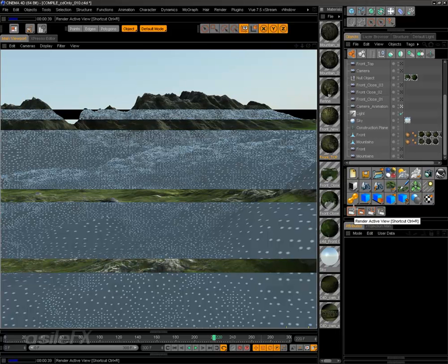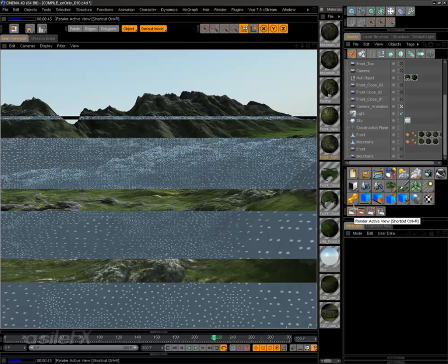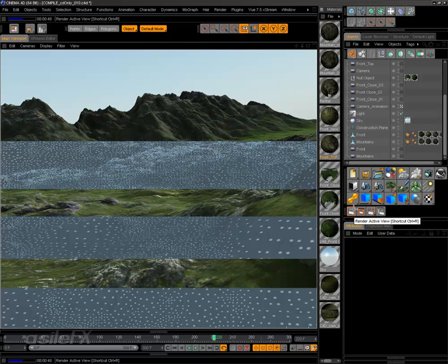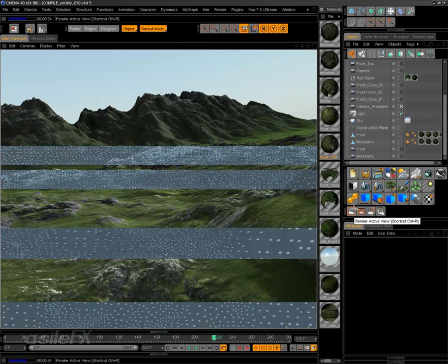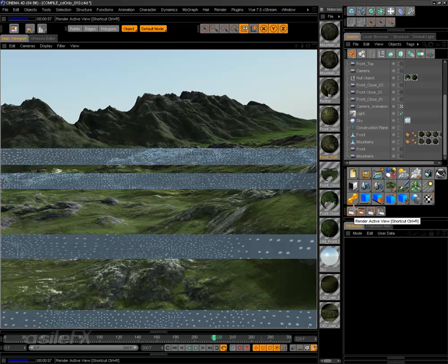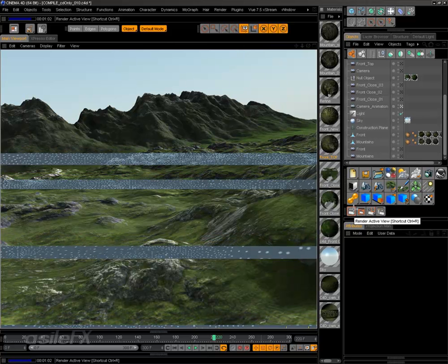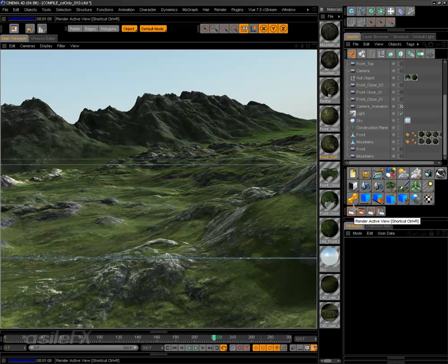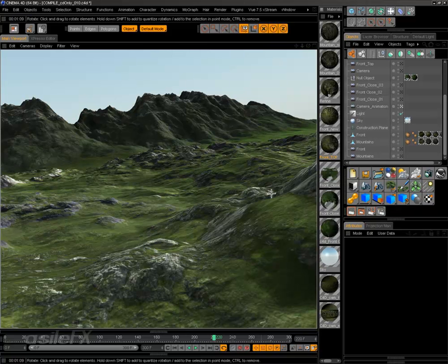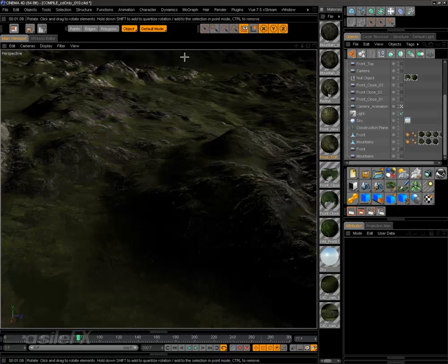Now, you don't necessarily have to use camera projection. Some of the stuff you could do just from the top, pointing down. I really liked using the camera projection for this and just setting up alphas, because I felt I had a little more control, because terrains are obviously going to be moving and have scale going upward. So in order to get the sides to have the correct amount of resolution and detail, I needed to come in from the side, which is more difficult without having to set up UV maps, and camera projection really turned out to be by far the best solution.